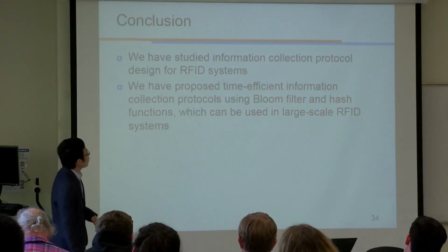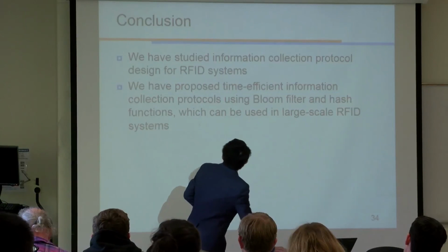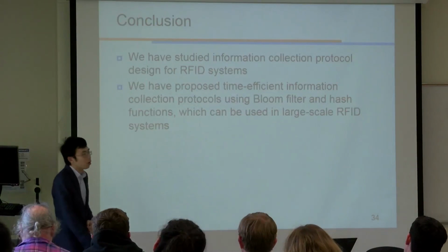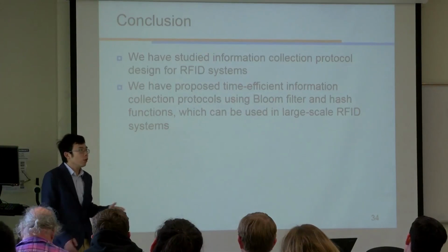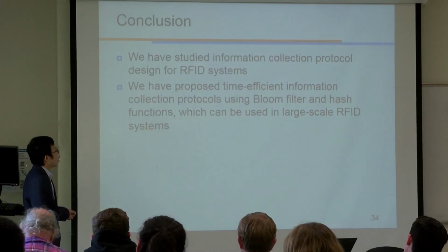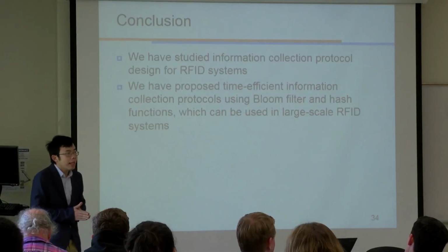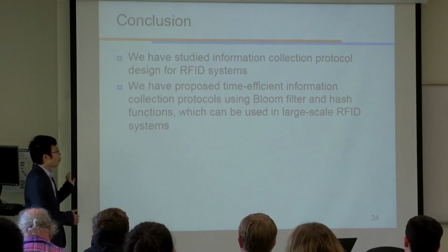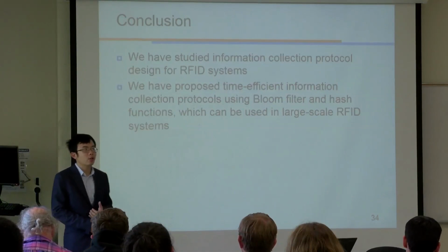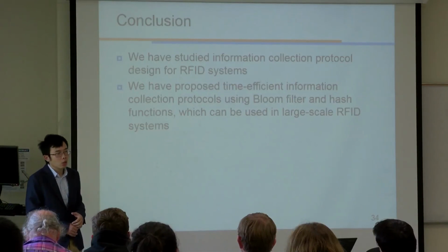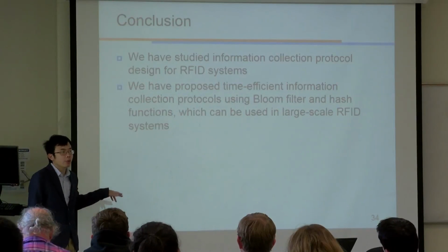Conclusion. In this work, we studied the information collection protocol design for RFID systems. We also proposed a novel information collection protocol using lightweight data structures like the Bloom filter, hash functions, and bit vectors to significantly reduce the running time of the information collection protocol.